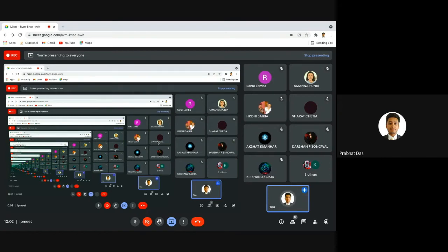First of all, we'll begin with a video which will be of 10 minutes in length. We'll play that video and try to understand how a touchscreen works, or how the technology of touchscreen works, with the help of that video. Later, after completing that video, we will go through the mathematical way by which we'll be able to calculate the number of PPI, or pixels per inch, in a touchscreen device or any kind of screen with X and Y resolution.